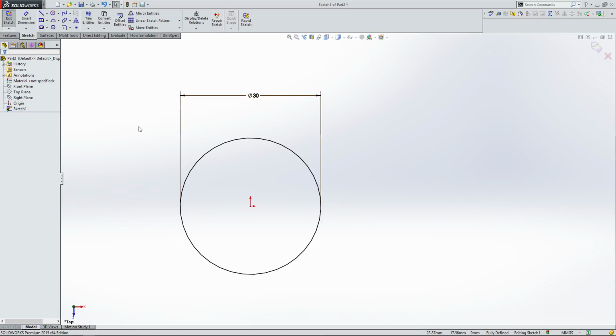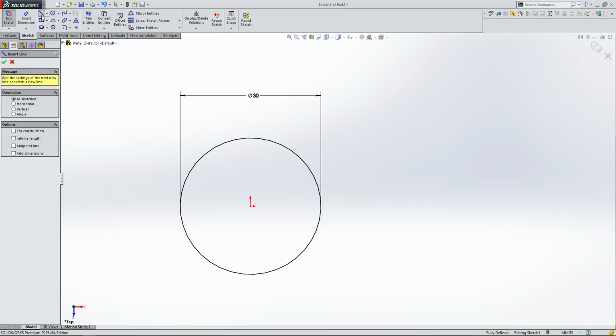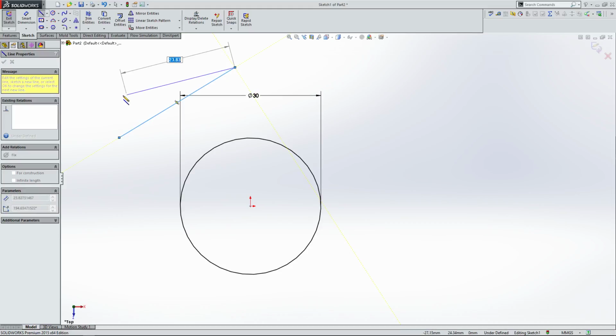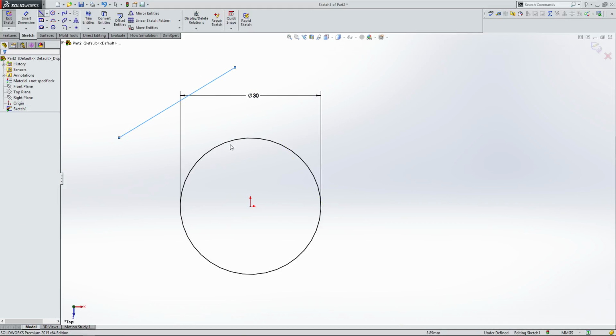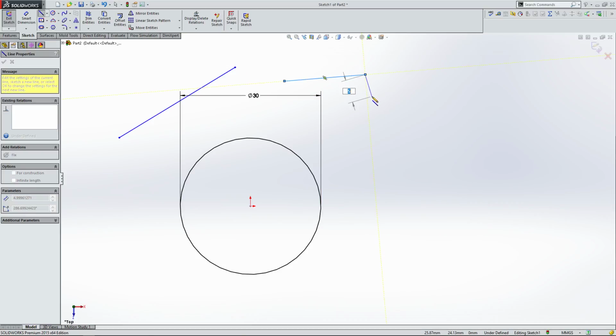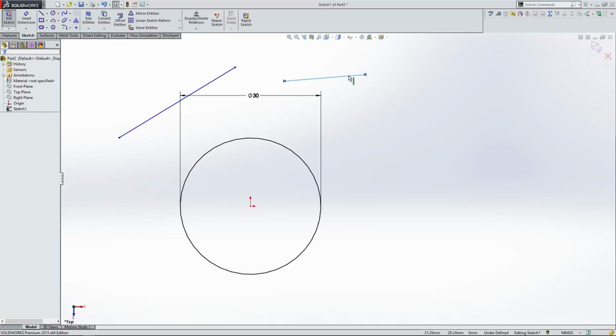And from here, if I want to, I can come up here and create a line. Just going to click and click again, and right click select. So now we're done. You can also, for the record, once you click down, hit escape on your keyboard, and that's going to get rid of creating a second line and a third line and a fourth line. It's just going to allow you to make one at a time.